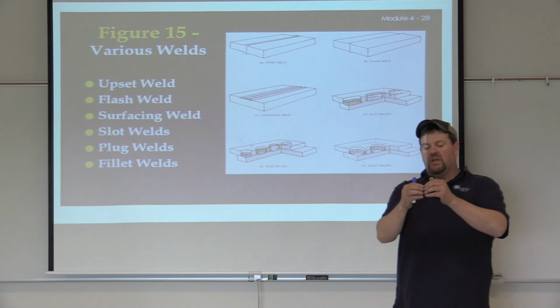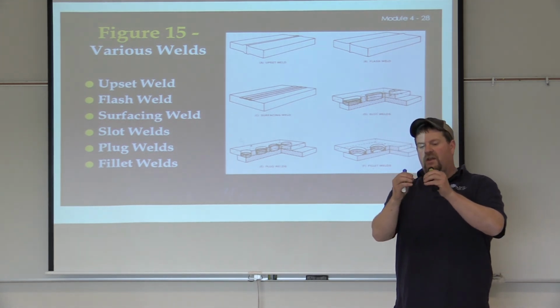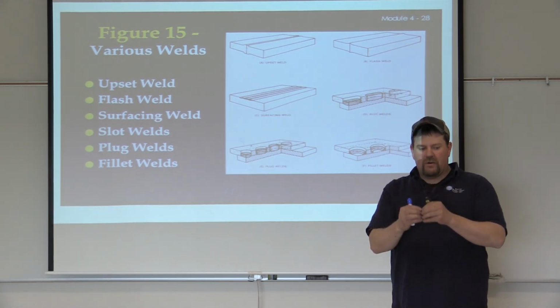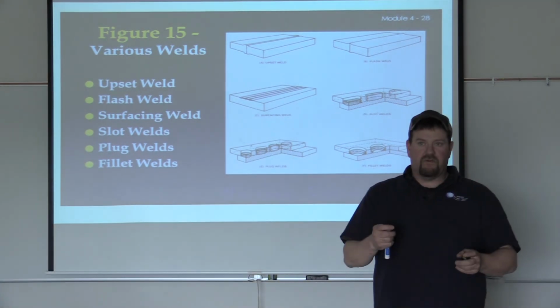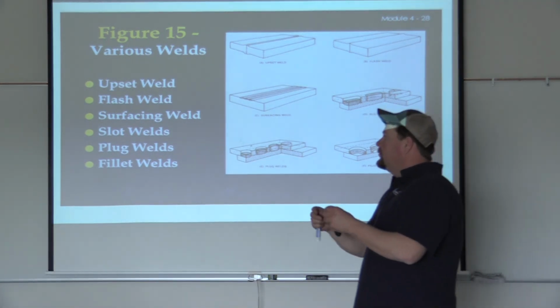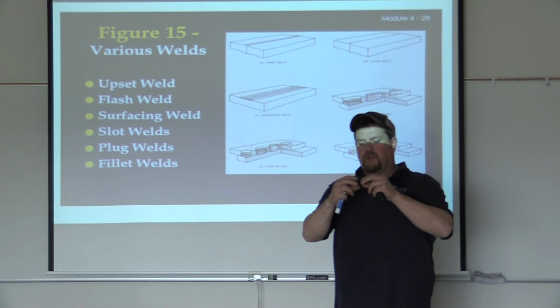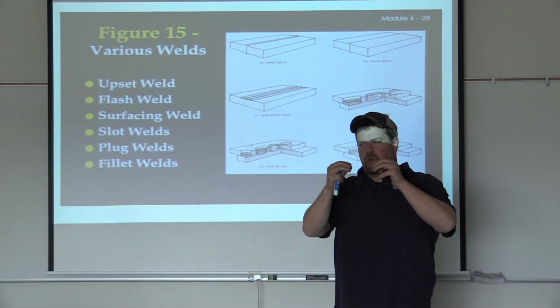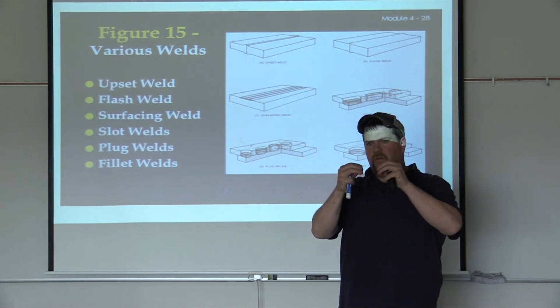Flash weld is actually just like the stud gun we talked about the other day. You take two pieces of pipe. It was very big in Russia for a long time. It was actually invented in Russia. You take two pieces of material, you bring them close together, you pull them apart with electricity, let them heat up and make each other molten